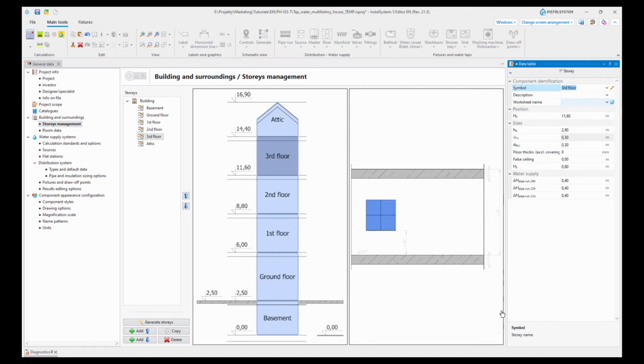So, depending on the situation, if you have already prepared the building structure or you build it together with the installation, you can copy only the installation, or you can just select, let's say, the first floor, and click on this button, copy. When you use this button, the program will copy all the elements, all the installations that are on the copied story.